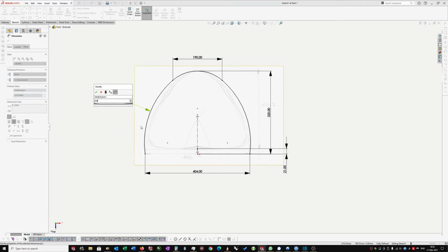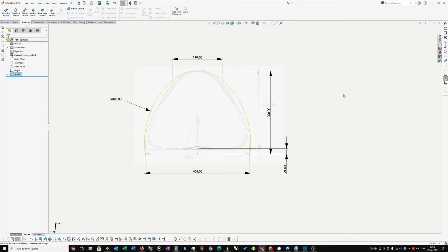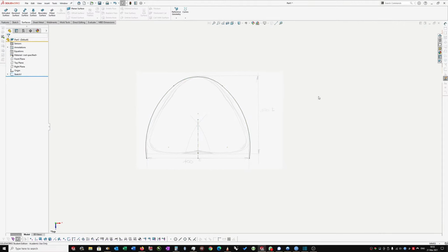It's looking better. So now it's curving in a little bit here on this edge, but it's still got this feeling of sort of a triangular seat. So I'm going to leave it like that because I want to try and make the video as quick as possible. So I've got a fully defined sketch. I've got this point which is going to possibly be useful later. The background sketch was just a guide. So let's hit the Escape button and then double click to get out of the sketch.